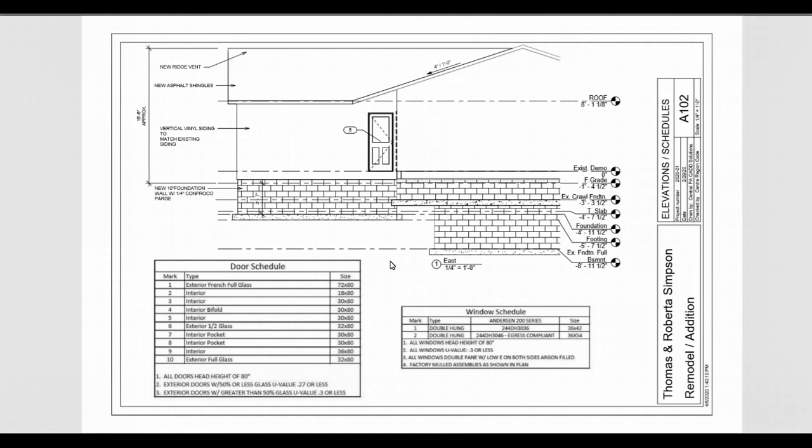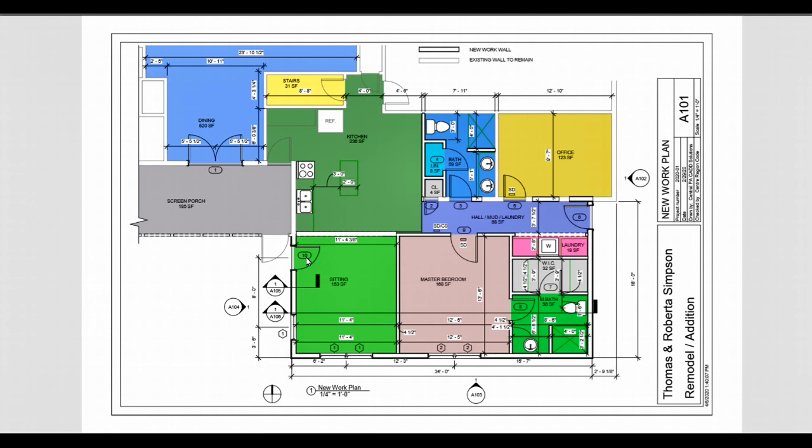But it's a real quick, easy way to look at this set of drawings, find out the information that you need. So if I'm a contractor, I'm going to purchase this door, and whenever I purchase that door, I'm going to look at my rough opening size that's listed on the manufacturer's recommendations. I'm going to make my rough opening size for that door that I purchase, and then whenever I install this door, everything's going to work out the way that it's supposed to be.